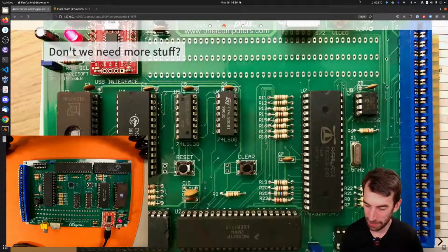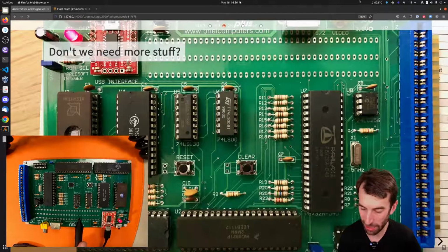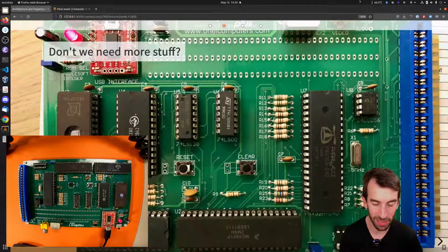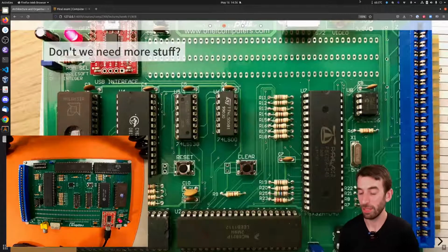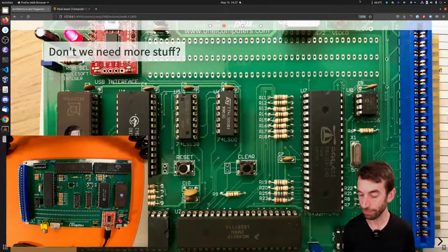Anyway, one more chip. It's hard to see what the words are on it, and they don't really help you at all. It's called a peripheral interface chip. So it's a chip which is going to help my computer connect to other stuff that's not memory and is in the external world. So it could connect to a keyboard, it could connect to some kind of other peripheral, and it's the one that's going to handle inputs and raise an interrupt line onto the CPU.